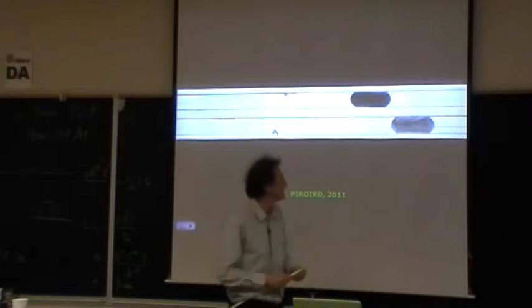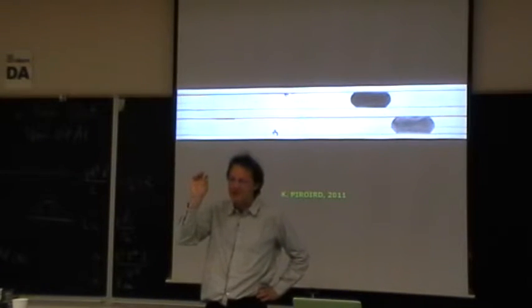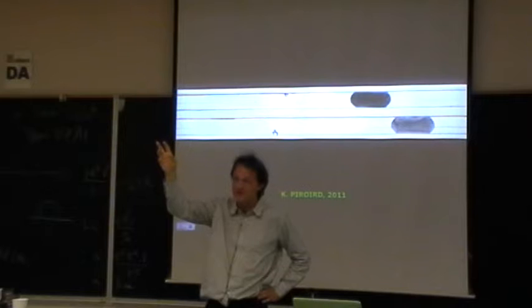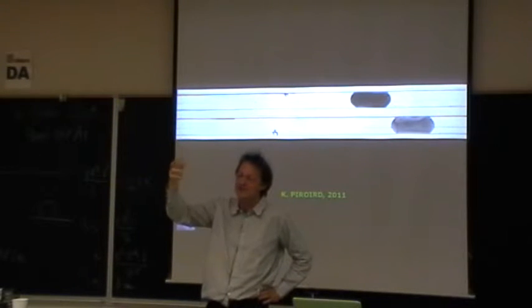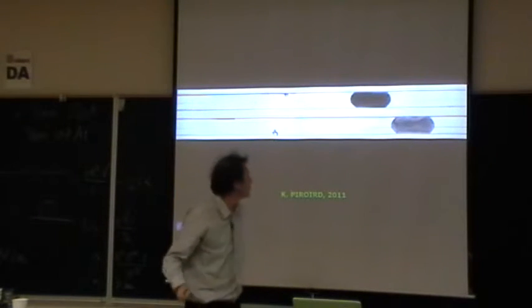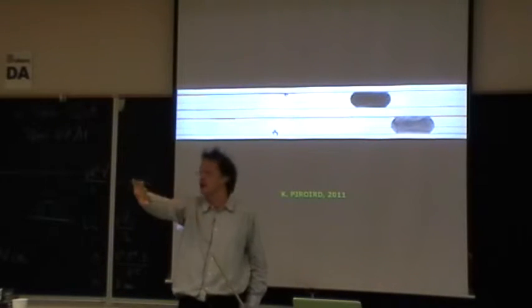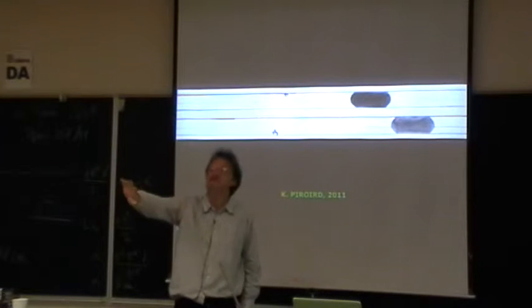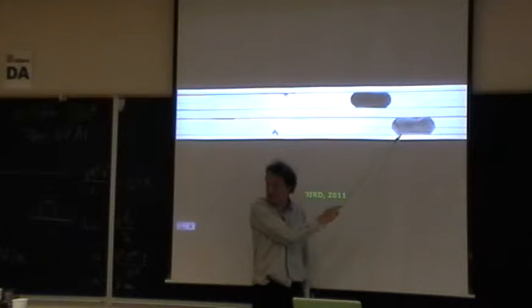The film, which is there, is much thinner. Remember the scaling that I wrote and I erased, which is that the thickness of the film should be sensitive to the velocity to the 2/3. So if the velocity is nearly linear in velocity, if the velocity is 100 times smaller, the thickness is 100 times smaller, which means that the quantity of surfactant that you bring behind is so low that it is diffused in real time. It gets diluted in real time. And so there is a possibility of generating a continuous motion in this case.